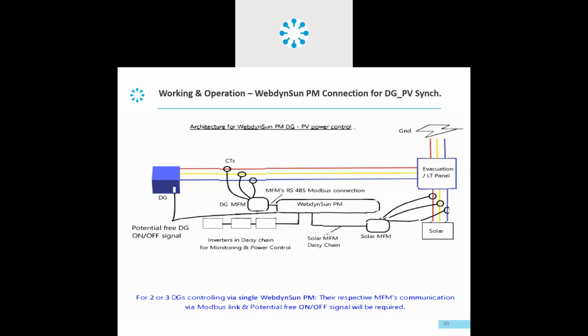As I've said, the response from our side is always 100 milliseconds and then the data is transferred down. That depends on whether the inverters are TCP/IP or Modbus in serial. If they are in serial, obviously the data is transferred one by one to every inverter. In 100 milliseconds it gives it, and then in a few milliseconds more. So normally in 2 to 3 seconds the command can be transferred to every inverter, and by that time the inverters start to go down or go up.